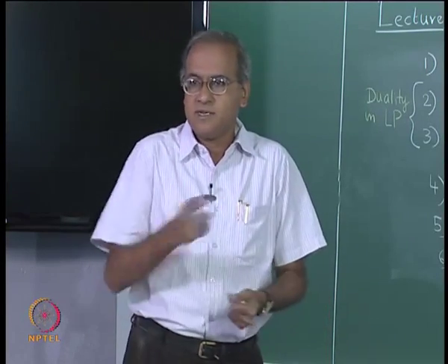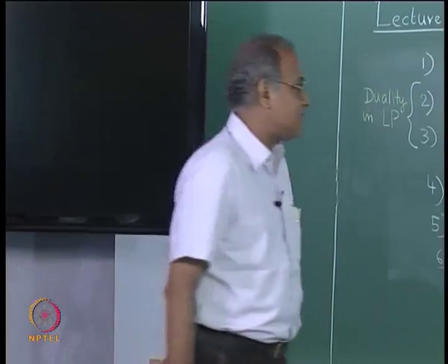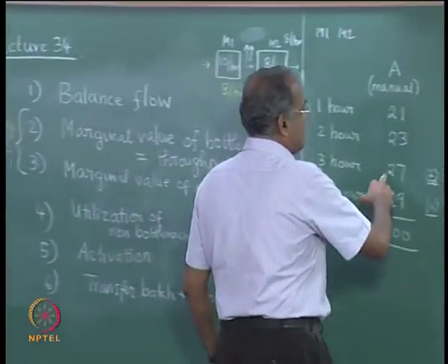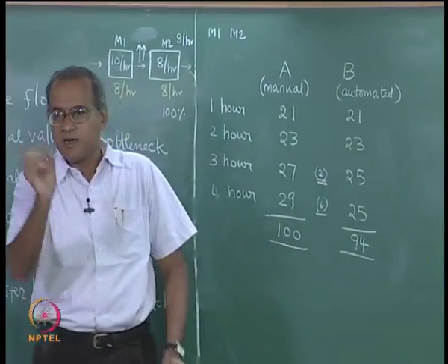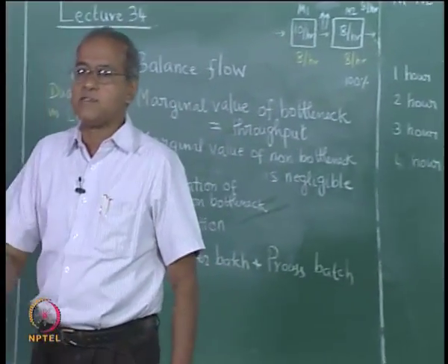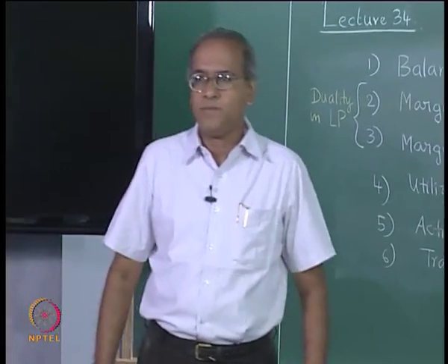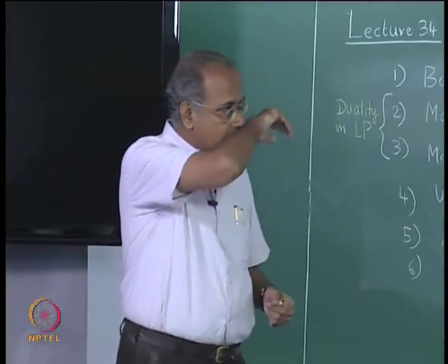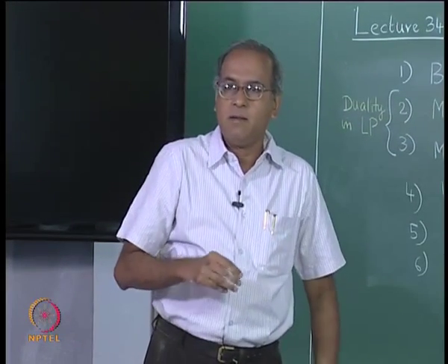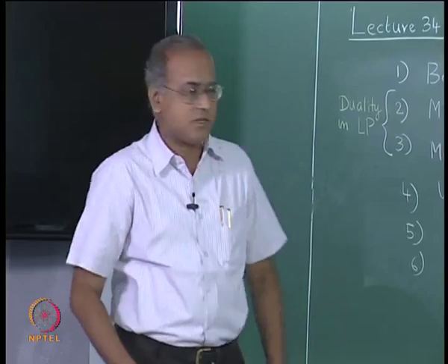Ideal situation is single piece transportation. So, this would have been done in 4, this would also have been done in 4 plus a small amount of time when the first piece arrives on M2. So, SM6 talks about transfer batch being much smaller than the process batch.